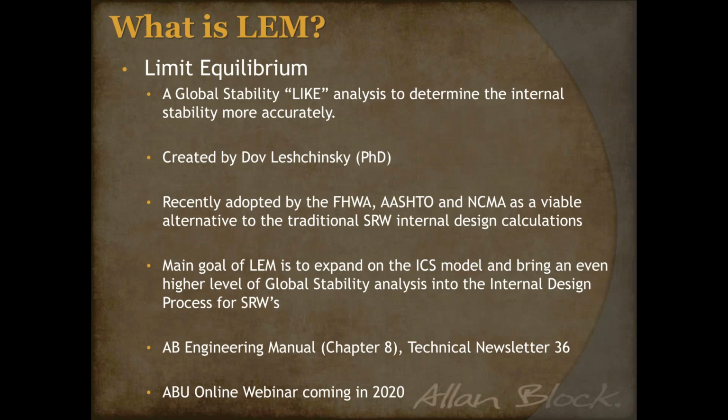All right, so what is LEM? I said I'd get into it, so here we go. LEM is a global stability-like analysis to determine the internal stability, or the accuracy of your internal stability. It is better: there's more calculations, more analysis, a better overall view of what's happening inside your internal stability. It was created by Dov Leshchinsky, and it has been recently adopted by the FHWA, AASHTO, and NCMA as a viable alternative to our traditional internal design calculations. Not that you don't have to do the traditional, you still can. This just gives you a little bit more in-depth look at it.